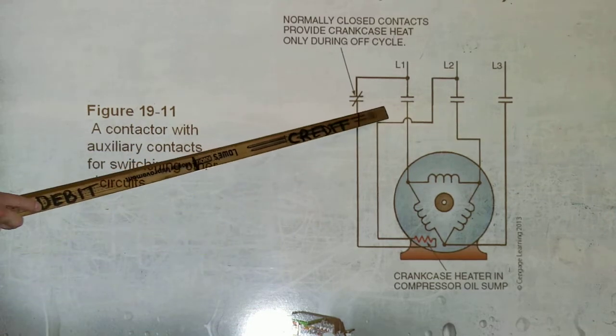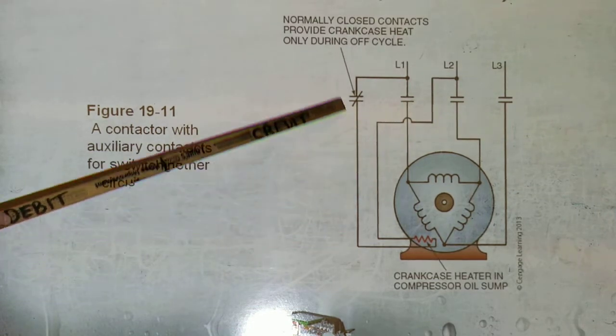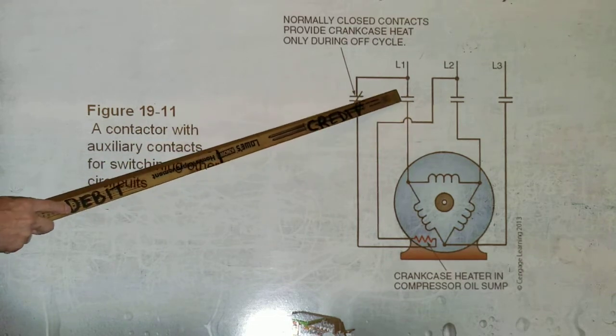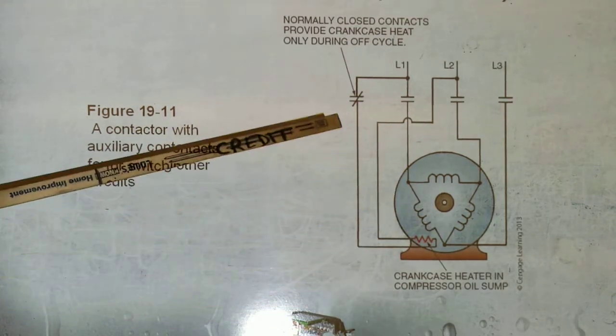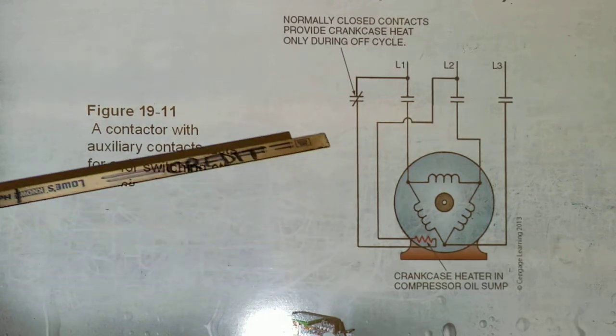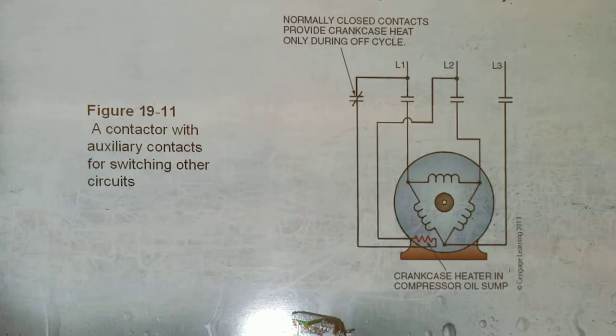The 3-pole contactor. Generally, if you have a 3-pole contactor, sometimes they'll have an option for an auxiliary contact that snaps onto that contactor itself. Just snaps on, locks in. Whenever that contactor closes, it pushes a lever down and it does something to the set of contacts, which is normally open or normally closed.